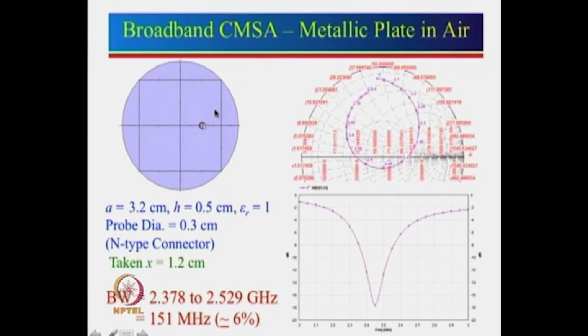Then there is another thing, that is, a metallic plate will have some thickness which let us define as thickness T. We cannot have a metal plate of 0 thickness. Of course, we can think about taking a thickness of, let us say, 0.1 mm, but a 0.1 mm circular disc will not remain stable, it will start warping and it will actually come down. So, instead of using 0.1 millimeter, we can use 1 millimeter thick, or maybe 2 millimeter thick or half millimeter thick.